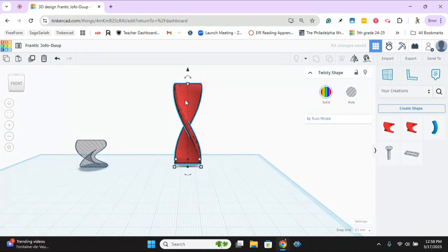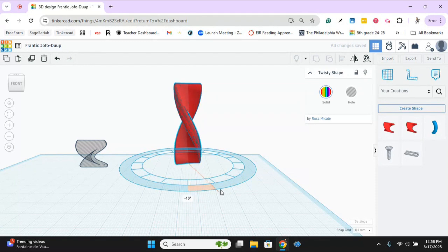Now that's 3 times as big. So now, once again, notice I have one shape here, not all the shapes that I used to have. So I'm not dealing with 181 shapes, I'm dealing with just that one, and that's why we create our own shapes. Now what I'm going to do is I'm going to duplicate this one shape, and I'm going to rotate it 45 degrees. Now to do that, I go right inside here. If I keep it inside, it gives me exactly 45. Out here, I can go by 1 degree increments, but in here I go by 22.5 degree increments. So right there is 45 degrees.